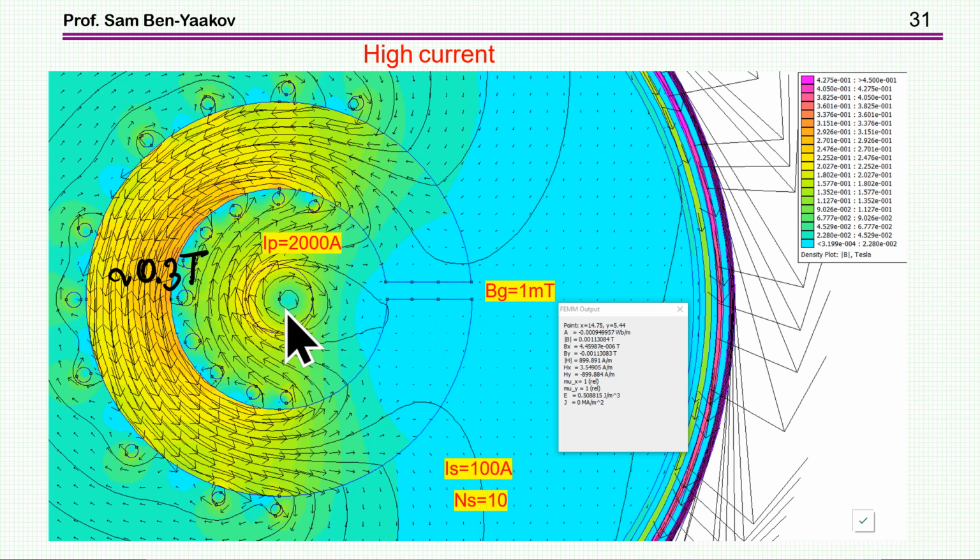So the higher current by itself should not make any difference, but it makes a difference because the core is now moving towards saturation, although the ampere turns are okay. You would have thought that if the ampere turns are the same, then there is no magnetic flux density left, but that's not the case. The fact is that in some region here, you do have a much higher magnetic flux density, and therefore it could saturate the core even though the currents are matched.